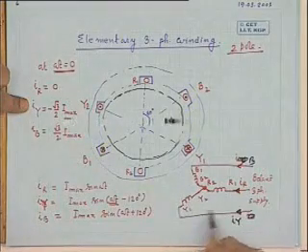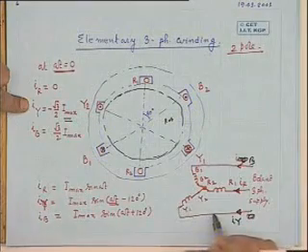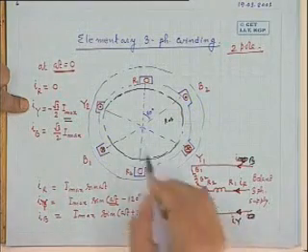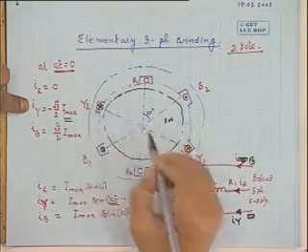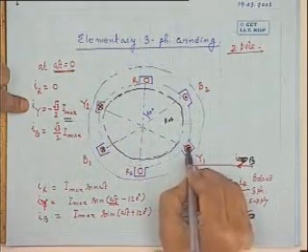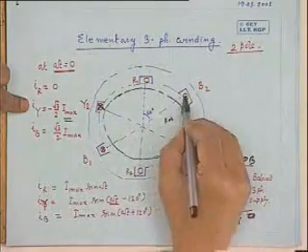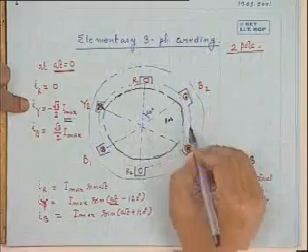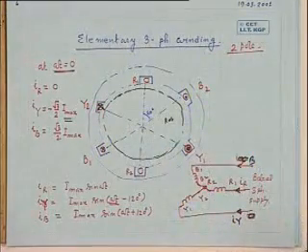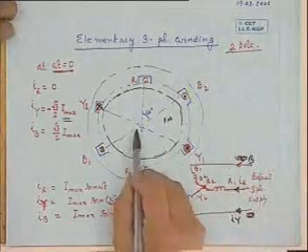And come to Y phase. IY is negative, meaning that current is actually entering through Y2 and leaving through Y1. So current is entering through Y2 and leaving through Y1, that is, this should be dot. So this is cross, this is dot, this is dot, this is dot.